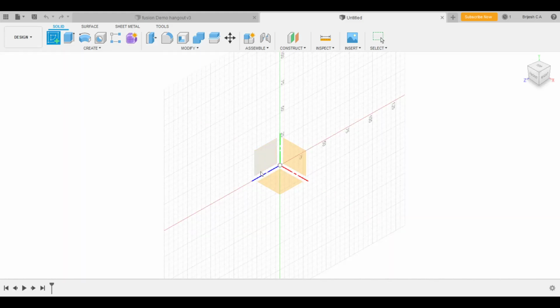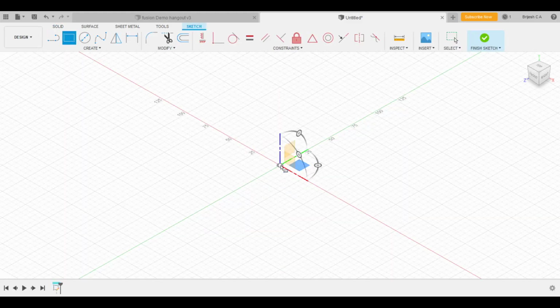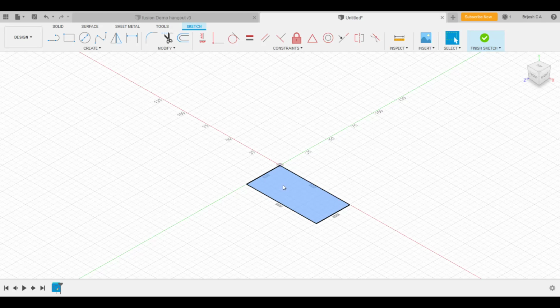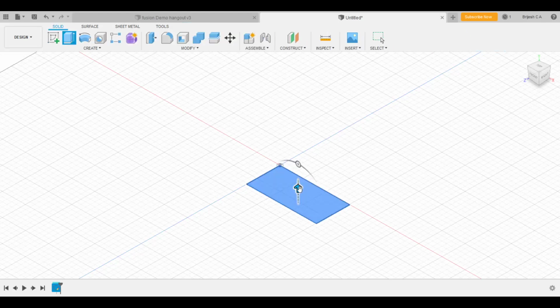Okay, quickly, I create a sketch, rectangle. Hold on. This extrude. There's only one option. You can either go up or down. There is no left and right. Okay. So you cannot move diagonally also? You cannot move diagonally. Suppose you want to move diagonally, there are different other options. So you have this option. You see revolve, option called revolve, or you have options like loft. We're going to come to it.